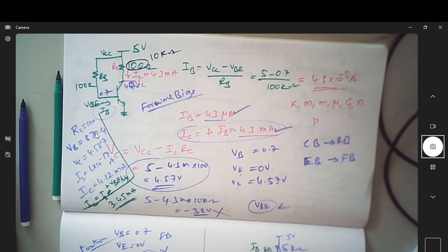The moment this becomes 874 millivolts, then this will become 4.1 milliampere, almost a 10% or 20%, 15% increase in the current, because it is exponential in the VB changes. So that's why biasing a transistor and keeping it immune to temperature variations or variation of other parameters is very essential in electronics. We'll see in the next video the other potential divider biasing for the transistors.